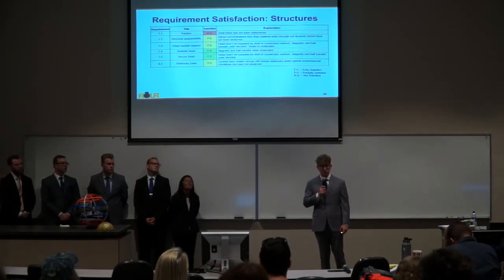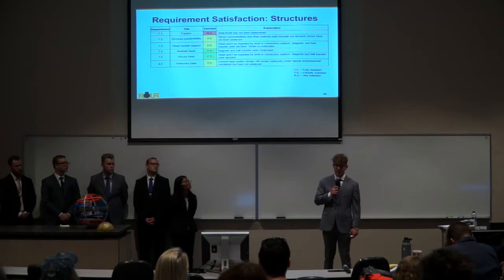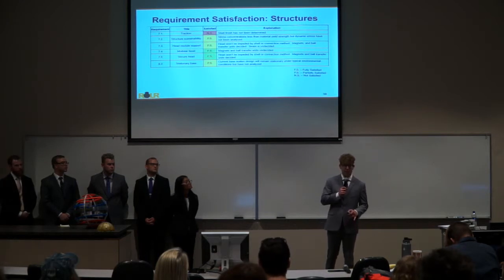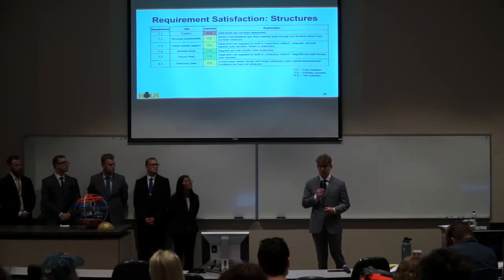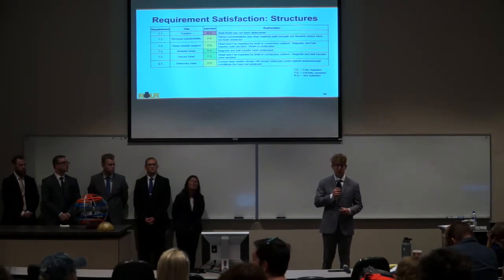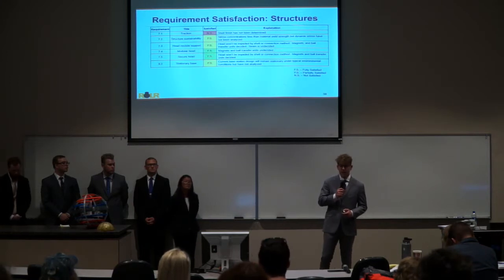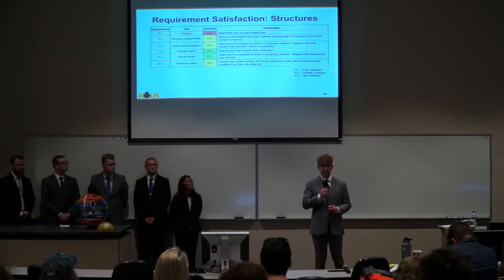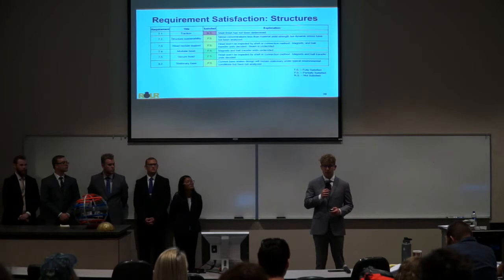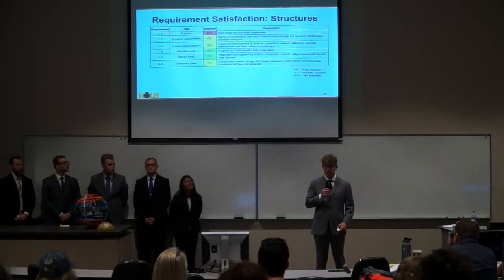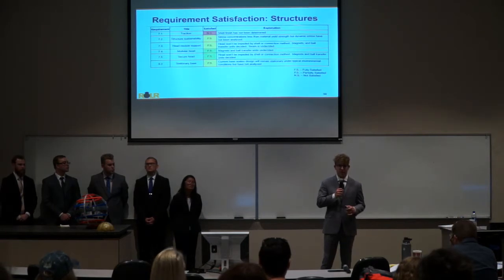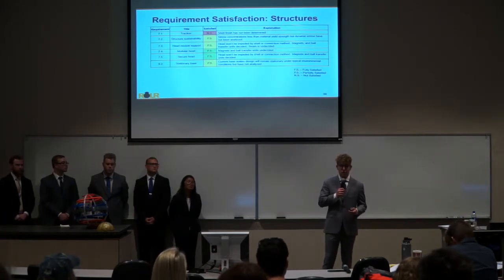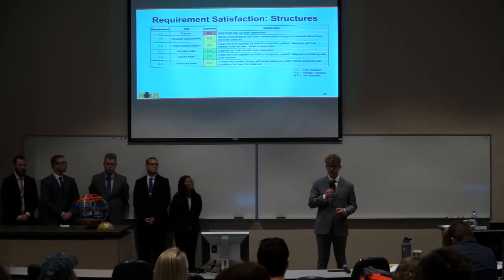Finally, we have structures. Traction is completely not satisfied because our use case, ROLR hill, has not yet been analyzed for what kind of coefficient of friction or tractional properties we're going to need in order to climb ROLR hill. Then we have our structural sustainability, which is partially satisfied, and that is due to the fact that we haven't looked at all the aspects of ROLR to make sure that it can withstand the 10 mission cycles in terms of structure. We have done a static analysis, but we haven't done a dynamic analysis to make sure that under actual rolling conditions, it will withstand the forces that it has to.